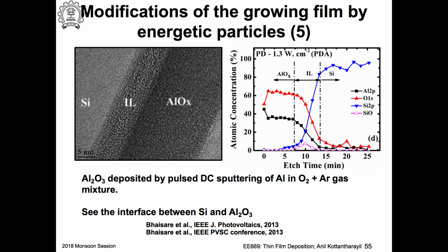So, aluminum would give characteristic peaks, but if it is aluminum oxide, that peak will be slightly shifted. So you can determine that it is aluminum and it is bonded with oxygen, and then what you are doing is you will sputter away this material and do this probing again using X-rays.